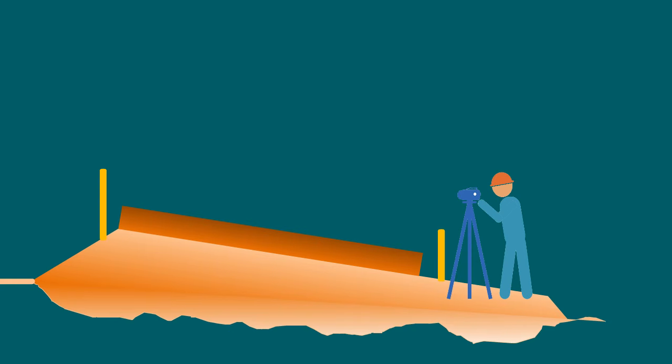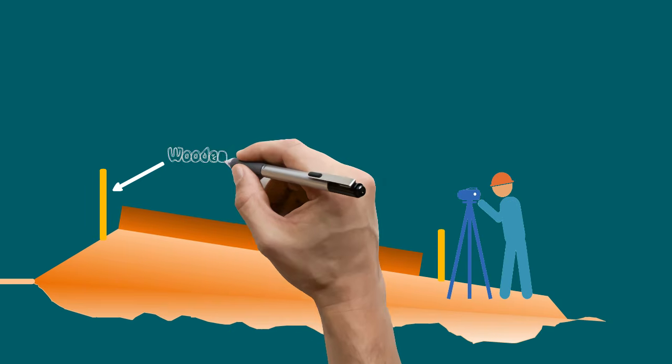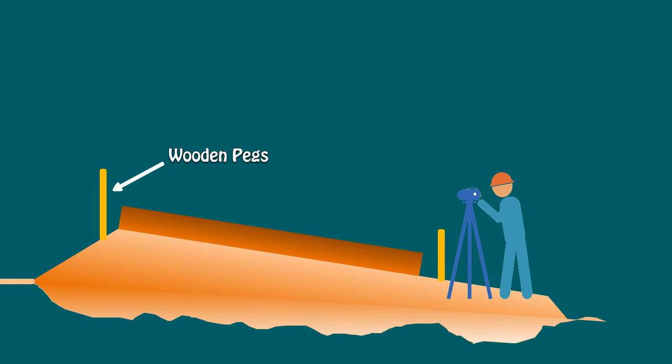Here, we will see the role of surveyors. This type of survey work is repeated in every item of work to control the width and thickness of every pavement, such as Wetmix and asphalt works. Before the commencement of any item of work, the toe line, that is, fixing of pegs to mark the limits of granular subbase, shall be done by surveyors.